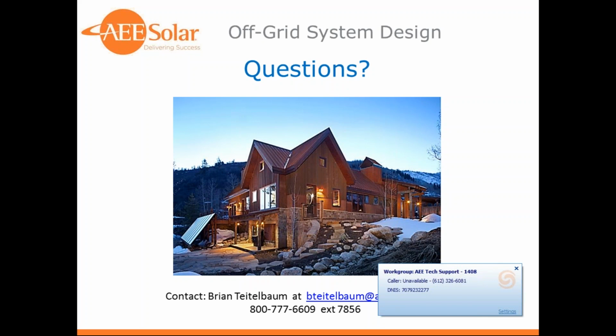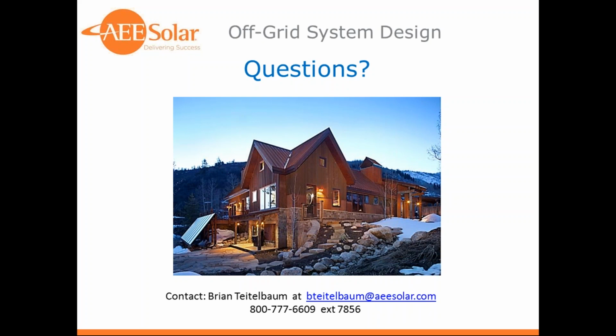One caveat with that is it's really important that people check the oil in the generator. Most generators have automatic shutdown on low oil, high temperature or something. It's important to not just think that an engine powered generator can just go on and off without any service. I often find with automated systems that people kind of forget to do service on the generator. But yeah, basic answer to the question, the systems can be programmed to have automatic generator start.